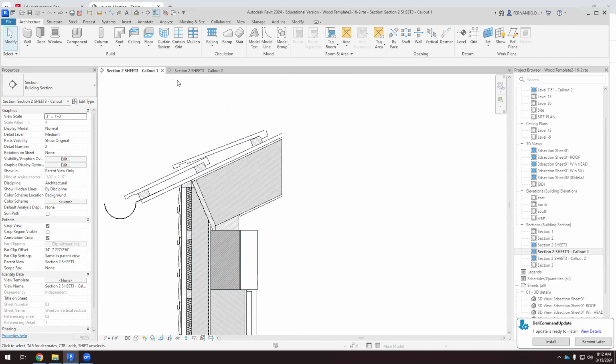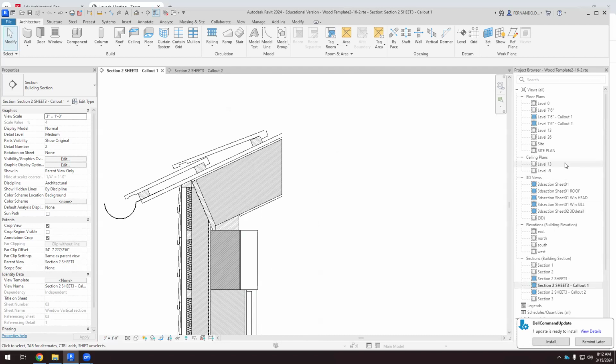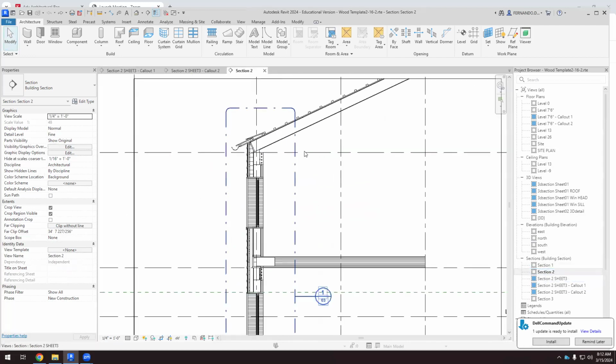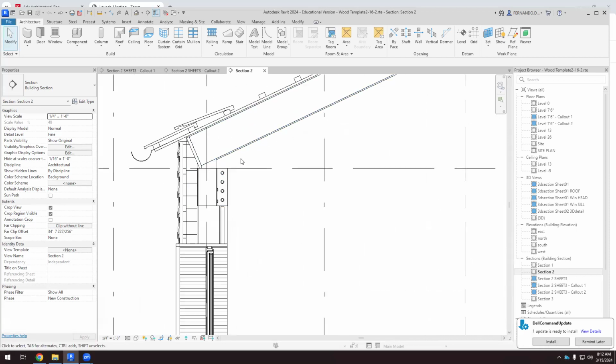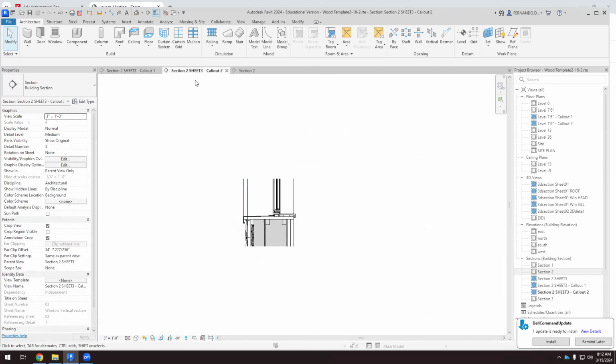So if we have enough space, just looking at the section, okay, so if this height is good enough, we can have like 2 or 3 inches of thermal insulation below the roof level. And with that, we can solve the thermal breach. Okay, so this can be done. So let's do this first and see what happens.